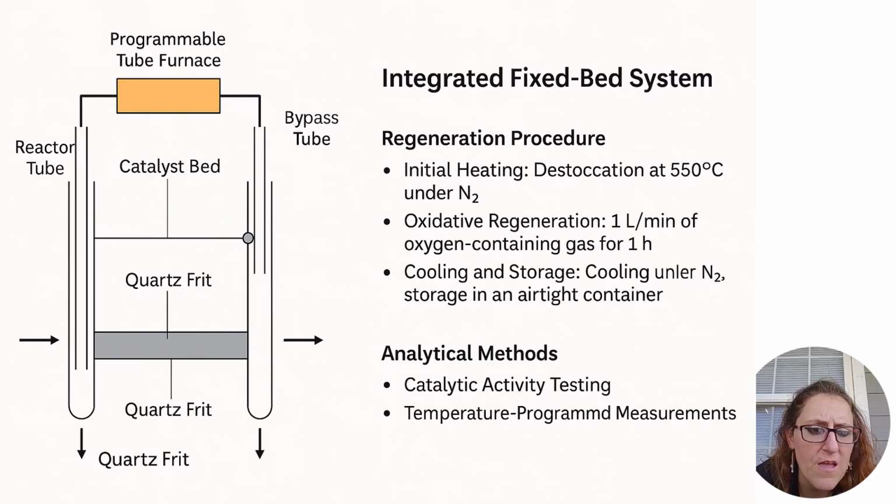Having both tubes inside the same furnace ensures that temperature changes are uniform, and switching between regeneration and testing modes is quick and precise. The uniform temperature profile achieved by the dual-tube furnace configuration minimizes thermal gradients, ensuring that the reaction kinetics rather than the temperature variations govern the observed regeneration behavior. The catalyst bed temperature was monitored using a K-type thermocouple positioned 3 mm from the catalyst zone, ensuring accurate thermal readings while avoiding direct contact with the catalyst.